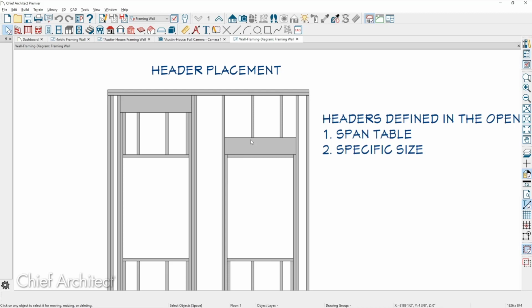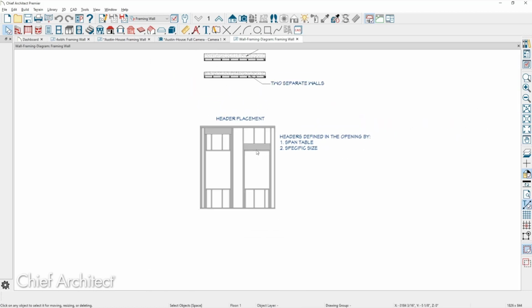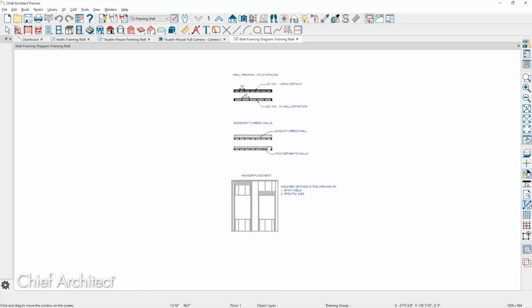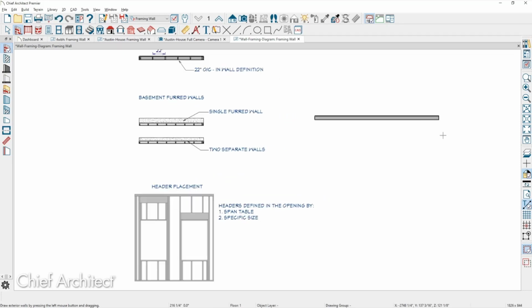The only thing that I can consider on that, I don't think there is, Scott, but if you use an I-joist for the header, that's what it's going to show. So rather than just use lumber, use an I-joist for the header. And then when you take a section like that, you're going to get that top chord of the I-joist. Can you specify the I-joist as the header with that width of the wall? That I don't know. I'd have to check.